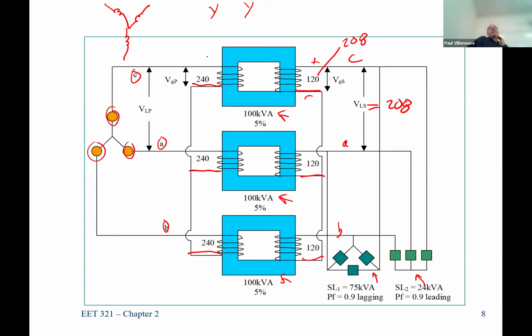Yes, sir. How can you do a phase converter? Super easy. Go buy a variable frequency drive. It takes, they break it down and reconstruct it? They convert it to DC and then they flip it out to AC for 3-phase. We have a senior project group this year that is doing exactly that. You're going to plug it into the wall at 120 and output, you get 3-phase, I don't know what their voltage is, but easy peasy. Well, I get a lot of power moving through it. So, yeah. Yep. But probably under $1,000, maybe $2,000. Just again, depends on the size that you need.